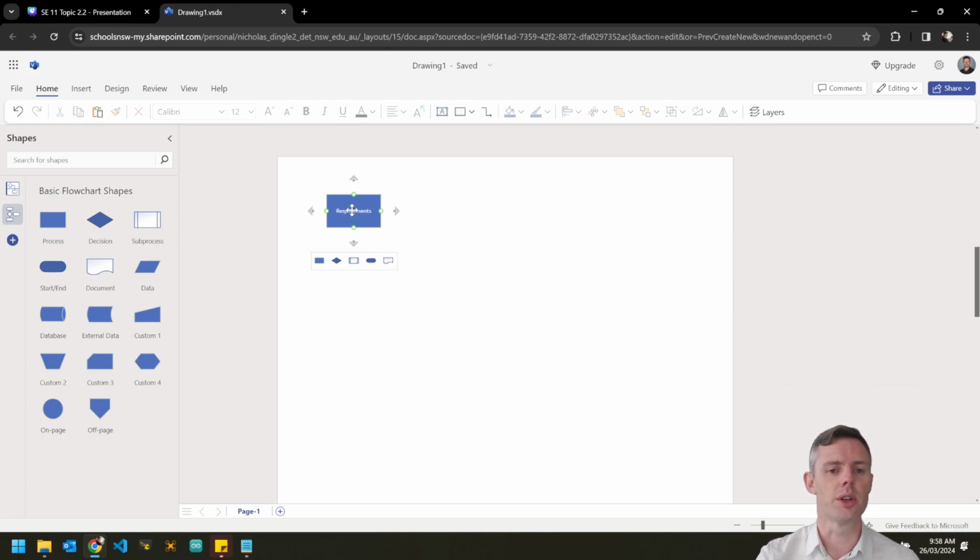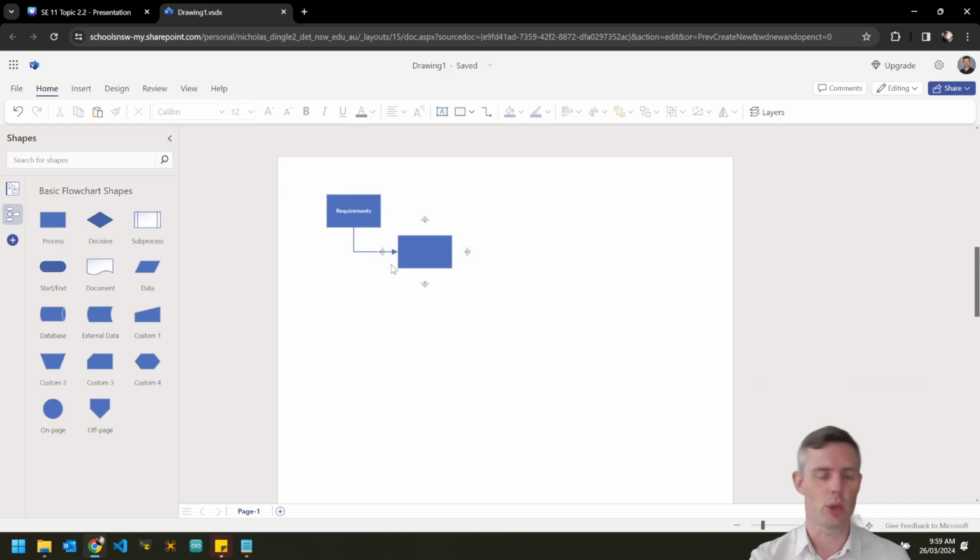And then what you can do to create the second step of our waterfall diagram, if you mouse over, you see you get these little gray arrows around the corners. Well, that's essentially saying what's the next icon that you want to produce for this diagram. So if I click it, choose the next diagram icon, there we go. And I can simply drag it around and that arrow, because it's now pinned to these little green and white points, it'll actually follow it around.